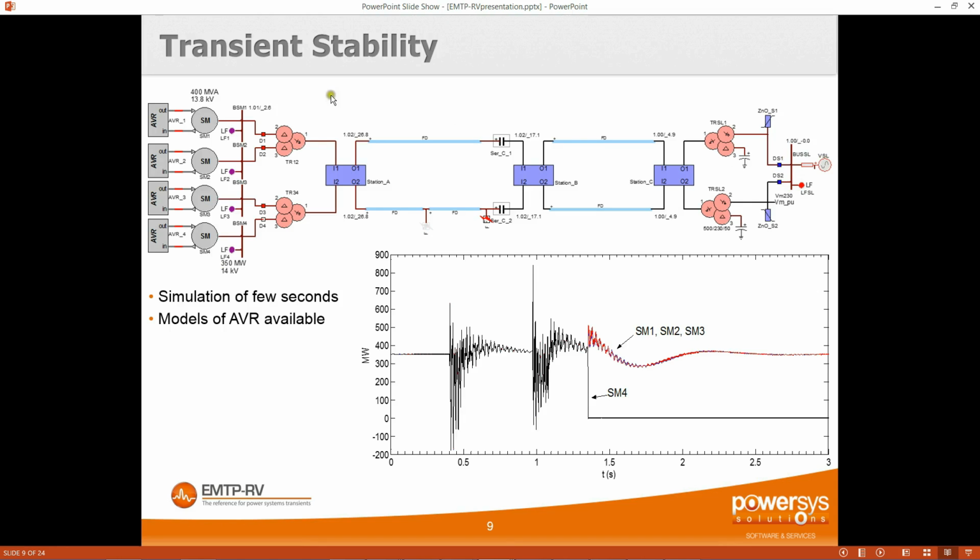The software will find all the results. You see here we display the positive sequence. It will find the result, the voltage at every node. And then we run the time domain simulation. It is automatically initialized with the result of the load flow. So it's great to save time. Everything is done by the software.